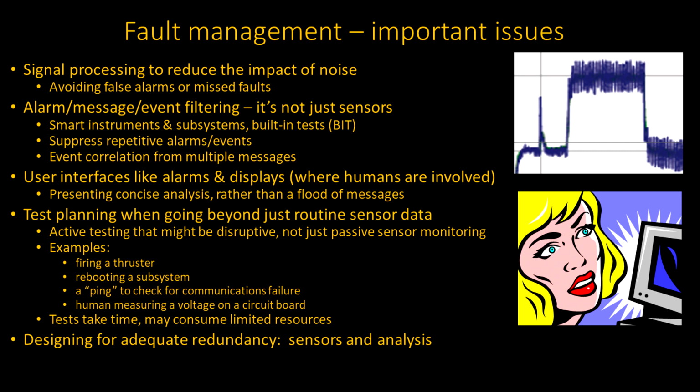Rebooting a subsystem. That's actually a common one on spacecraft and, well, every kind of equipment, really. Because memory gets corrupted or bugs corrupt the memory in one way or another, rebooting takes care of things. If you reboot, and the problem goes away, then that tells you, okay, you had a problem with either a computer bug or maybe a radiation-induced memory problem. But either way, you've identified it. It's not just a fix. It also is diagnostic information.